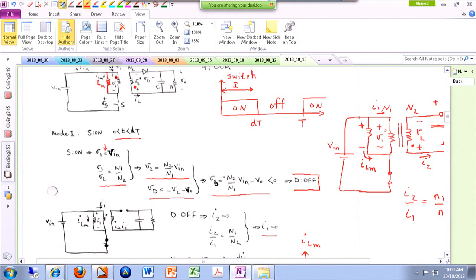All right? And by the way, this is the way we model the system. So if you really look at the system, it's sitting on the table, you can't really see LM. LM and the primary side are basically the same thing. So you cannot independently measure ILM. So please remember that. ILM is like a fictional thing that we are trying to model the system with. So all you can measure, if you really have this system sitting on this table, is this current and this current.